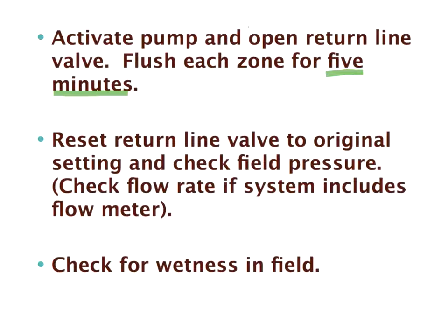Okay, reset the return line valve to its original setting, because it might be that the valve is being cracked open. It might be a manual valve that's being cracked open for continuous flushing. And check the field pressures, and that they're now back to the right pressure. Because if you're cracking open your return valve, if it's too wide open, you're going to have your field pressure drop too low. And check your flow rate.